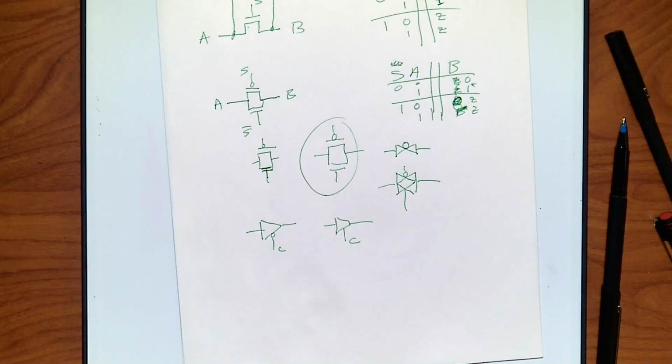With one simple little gate, I can give you the control signal: are you allowed to talk? So think about when you typically have a network or a bus situation, there's usually some controller to the bus that's saying who's allowed to talk at the moment so you don't get crosstalk on your network and shorts and all kinds of other problems. Right? So one way you could do it is the bus controller could send a signal saying your turn to talk. They give you a token, they give you a high line, whatever, which tells you your turn. They can send your address and you can decode that. Right? Lots of these options.